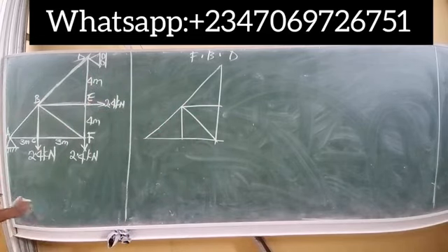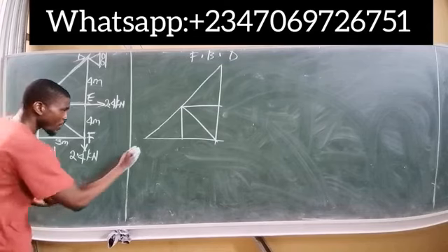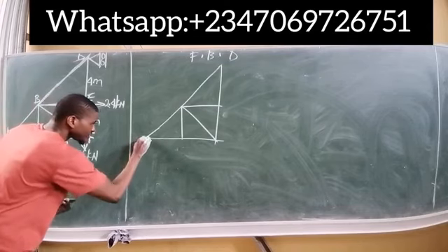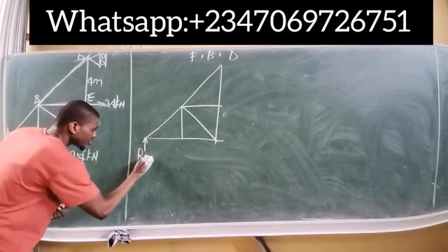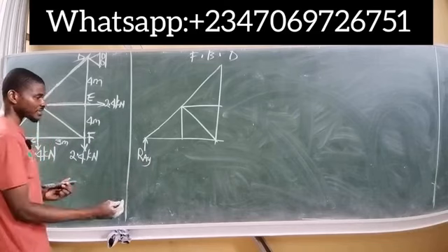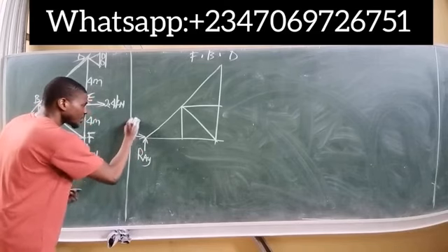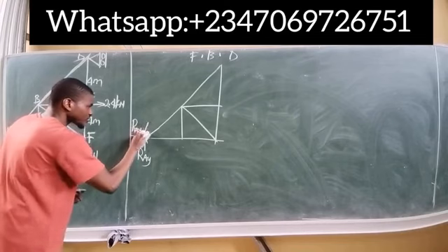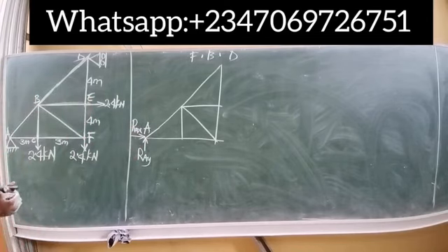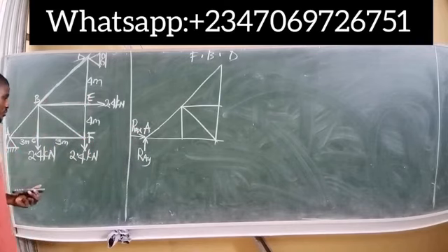Now at point A we have a pin, and for a pin support we always have two reactions. One of the reactions is vertical, so this is simply RAY. So the reaction at point A, Y signifies vertical, and then the other reaction is horizontal, so we simply call that RAX. So for a pin support, we always have two reactions, one vertical and the other horizontal.